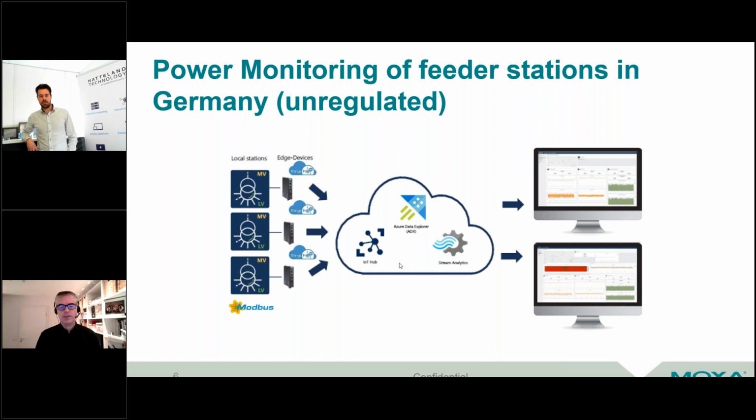Well, with renewable energies in the local grid, the distribution network, the low voltage network, additional more or less unpredictable loads have come on the network. Electrical vehicle charging stations are also directly connected to this low voltage network and present a load that wasn't there before. So really this local grid is used for things it wasn't designed for, and at the same time there is no sensoring and monitoring in that local grid that would allow the operator to react flexibly. And that's what this is fixing.